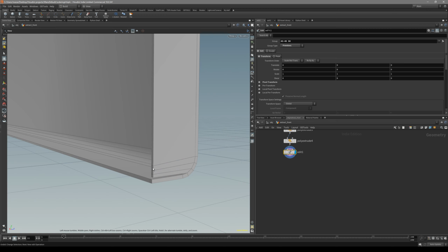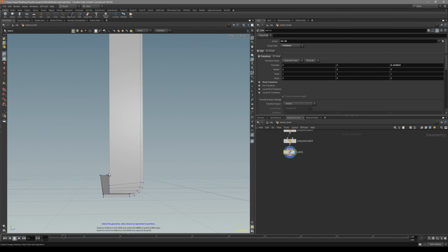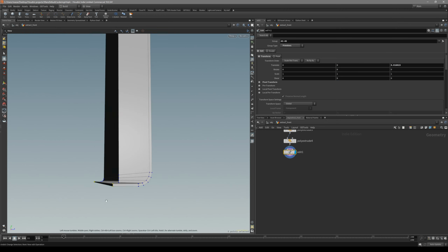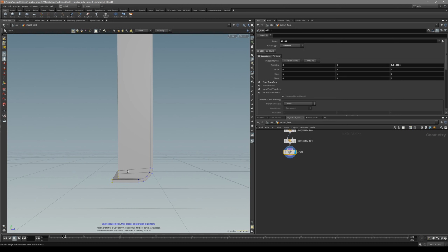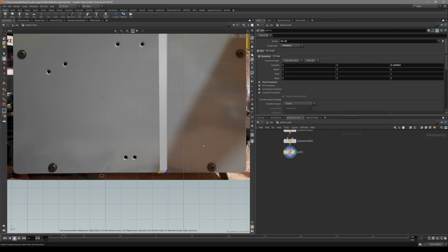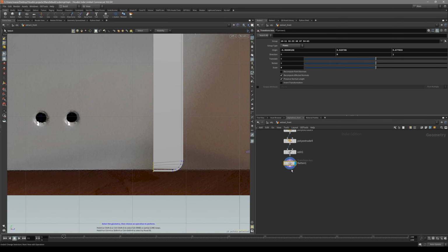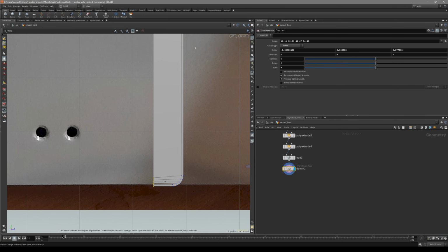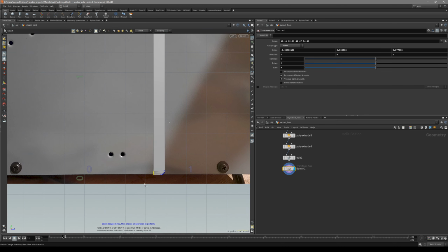If you have Modeler, there's a really awesome tool for us to use. So let's move these around. Let's say I want to align all of these back with the very back of these polygons. So let's go to the side and select all of them like this. In the Modeler toolkit there's a flatten option, and all we really have to do is select the polygons, edges, or whatever you want to flatten, and then flatten to the left, press on it. You can see it's going to put down a transform X automatically. It's going to flatten to that place. So this is a really big advantage for the Modeler.